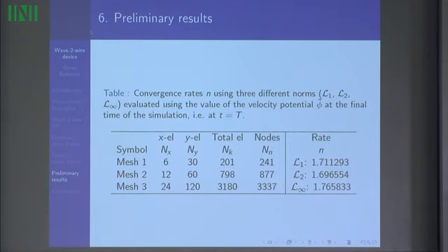Now the spatial convergence, you expect 2 because it's just standard continuous Lagrange finite elements, and the order is 1.77, so it's not quite the order 2 in different norms. Actually, we did another one just recently, and they all uniformly get close to 1.77 once you halve the mesh size. So for all the norms, for the L1 norm, the L2 norm, and the L infinity norm.